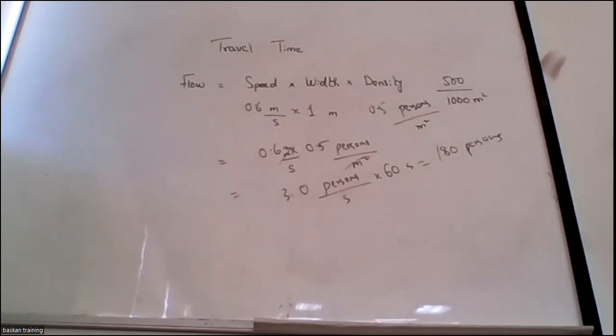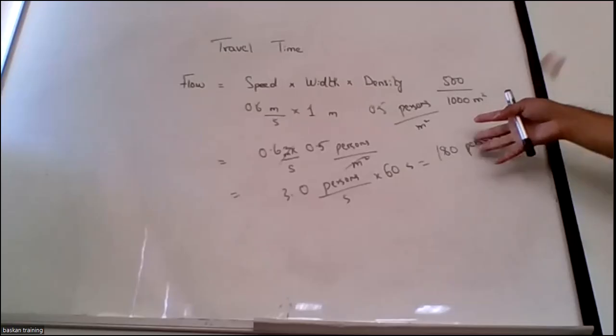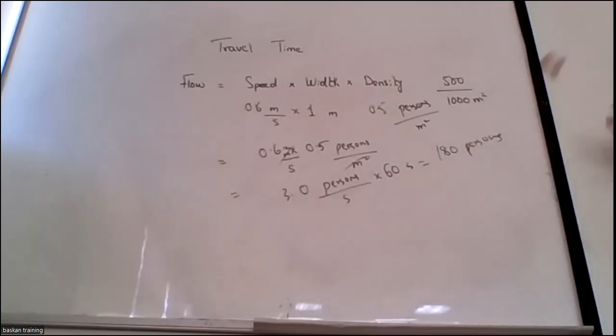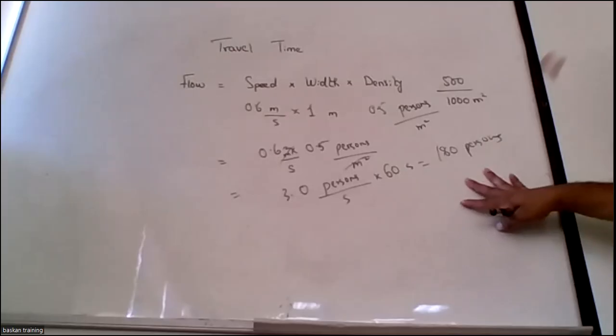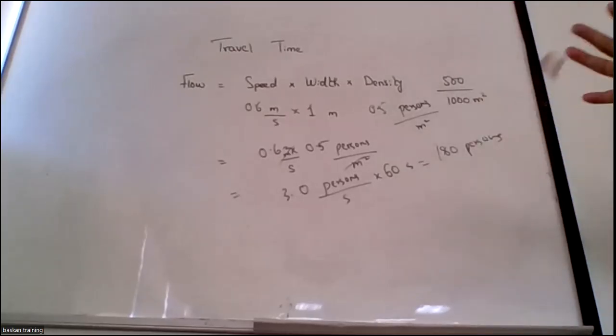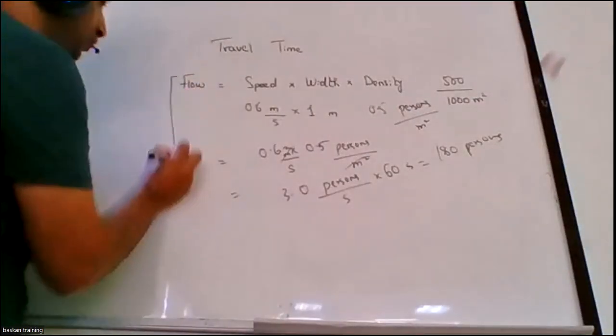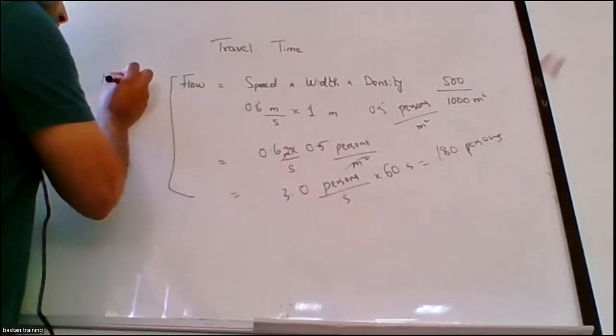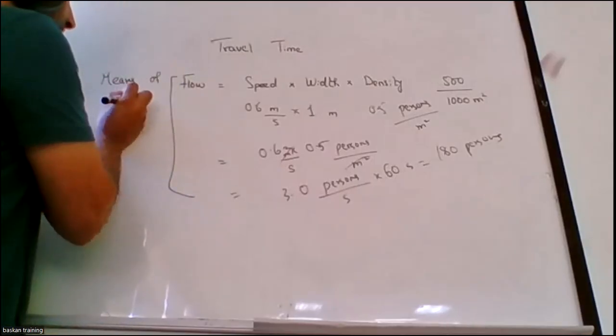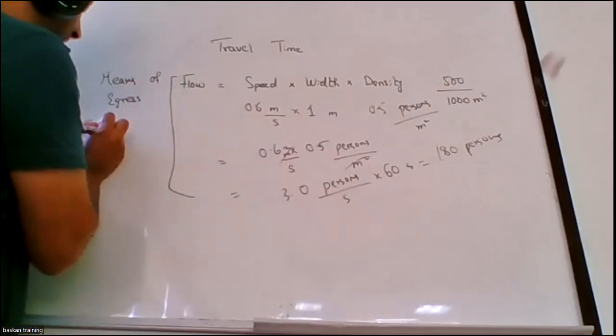For a residential occupancy it works, but in the Dubai Mall or Global Village it is not going to apply, because the crowd is too much. There we move on to the next strategy, which is the movement models. We will discuss that also, but travel time can be calculated like this. It is usually said that means of egress can be calculated in two ways, two models. One is the capacity model, and this is the capacity model.